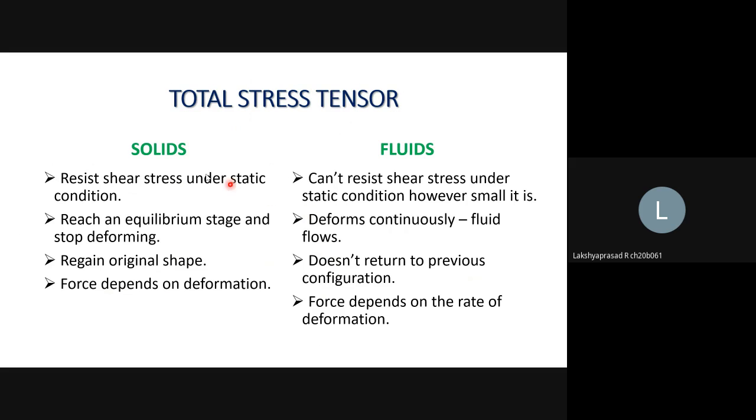So we are coming back to fluids from solids. It is important to understand what's different here. Solids resist shear stress under a static condition. However, fluids cannot do so, however small the shear stress is. Solids will reach an equilibrium stage after some time, and they'll stop deforming. However, that is not the case for fluids. They'll just flow. They'll deform continuously.